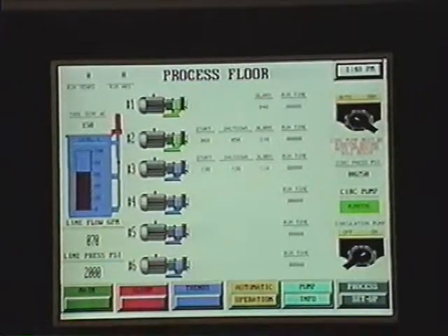Pumps 2 and 3 were still running even though they were in alarm. Pump number 4 then becomes the new pump number 2, 5 the new 3, 6 the new 4, and so on. But now we're just showing enough to keep pumps number 1 and 2 running.